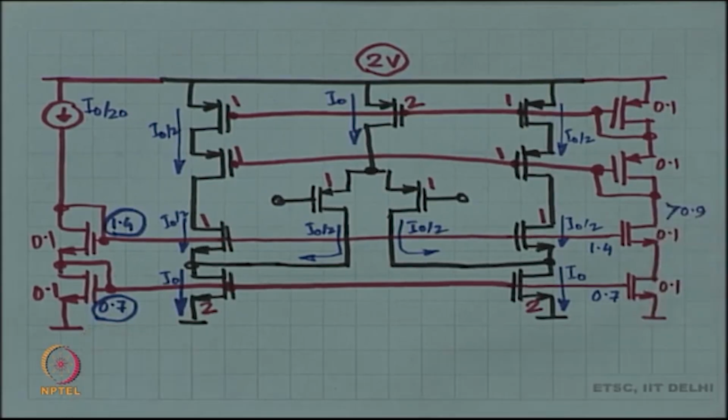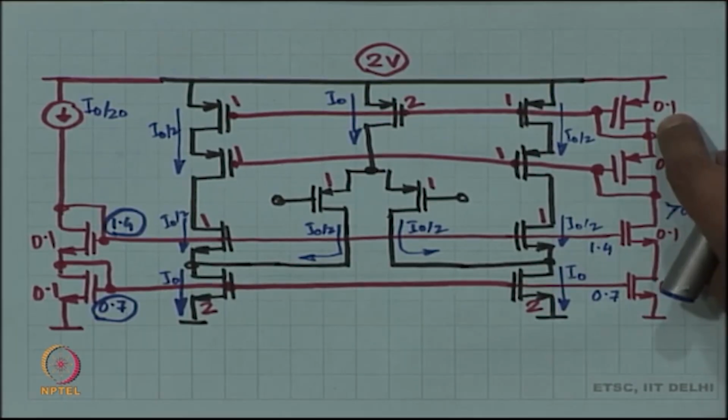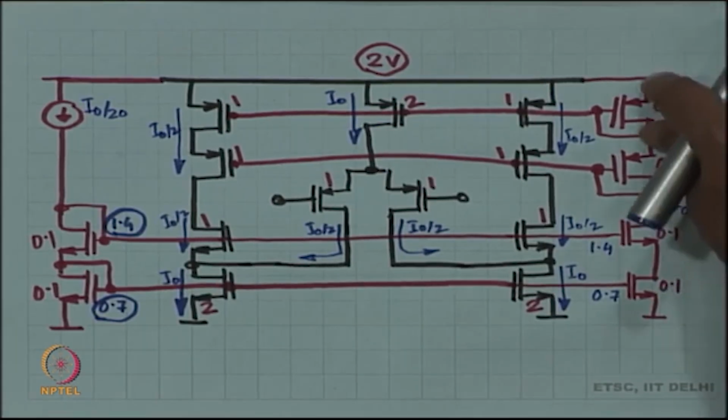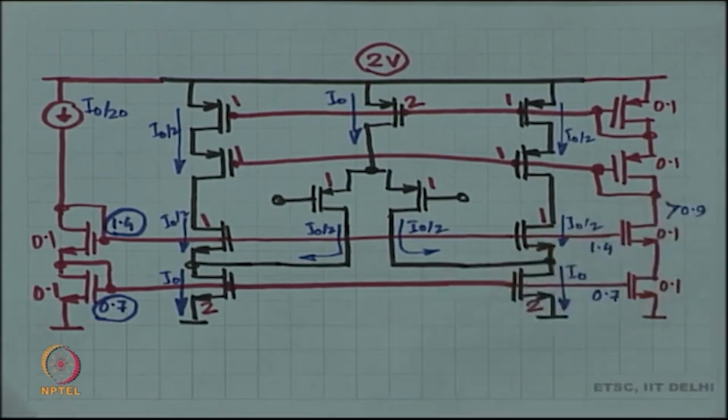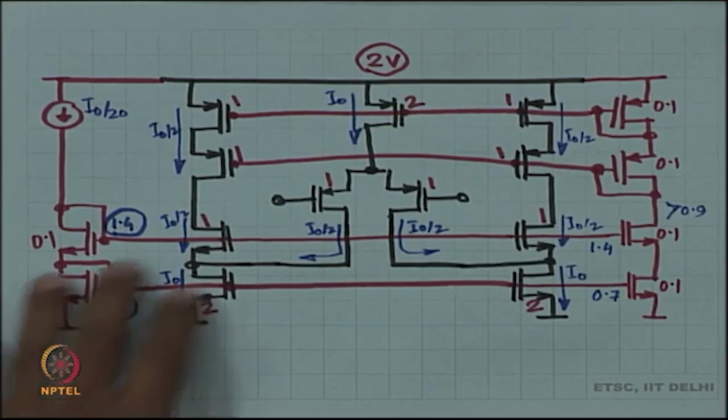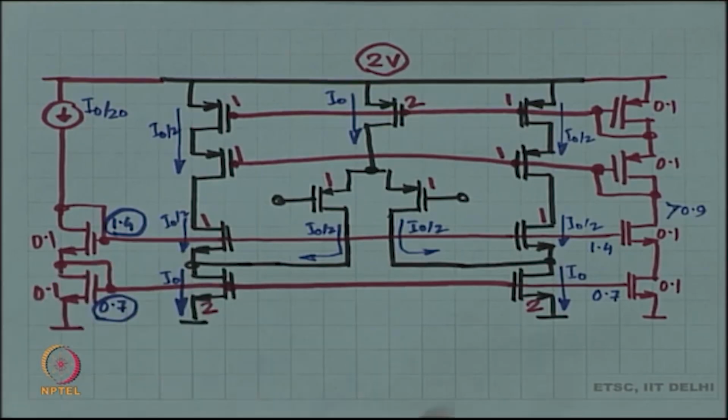Okay, but does this work out? For your PMOS, you need 0.6, 0.6, and as a result the required voltage is 0.8. So, you have a problem, even before you start you have a problem. So, this Wilson current mirror is no good. Alright, you need to be a little more aggressive, you can't be using Wilson.